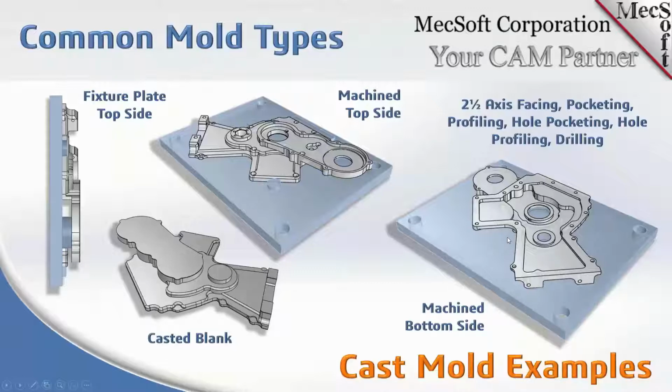as your finished product, because you're going to be machining this blank in areas that are functional for this part. So in the top and right areas, we show both sides of this blank after they're machined. So you've got machining on one side, and then you flip it over, and we have fixture plates to illustrate that process. Again, if anybody's got any questions, put them in the chat window, and we'll get to them.